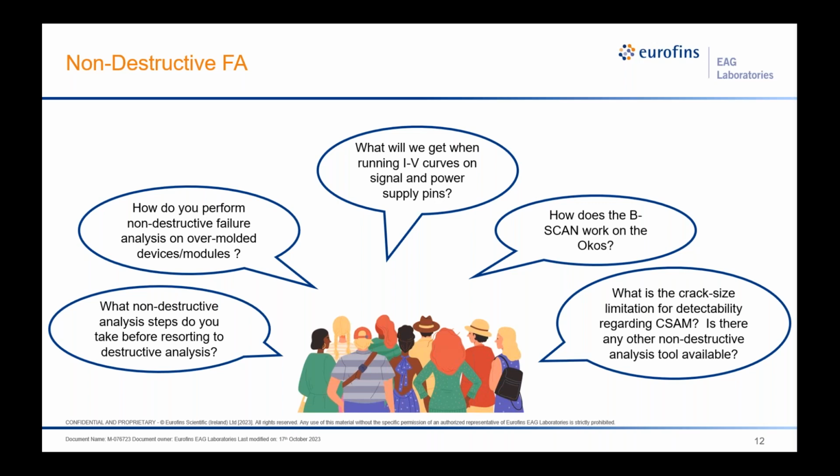Sure. So the initial non-destructive steps are a good way to assess if there are any construction or assembly related concerns. Depending on where the sample came from, you might even want to assess if there are signs of contamination, package integrity, mechanical stress. Sometimes we want to verify the failure before any steps that may alter the behavior of the device. So if there's something that might change because of thermal stress, might change because of mechanical stress, we probably want to record that before we do any of those steps. And this may even give us some invaluable insight about the actual failure mechanisms, which may change the direction of the next steps of the investigation.